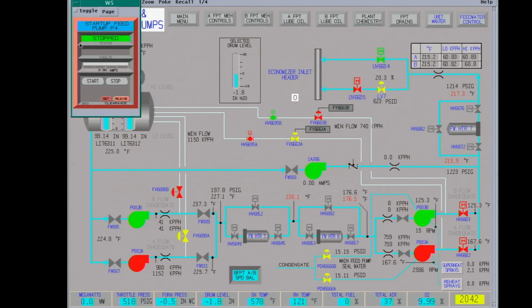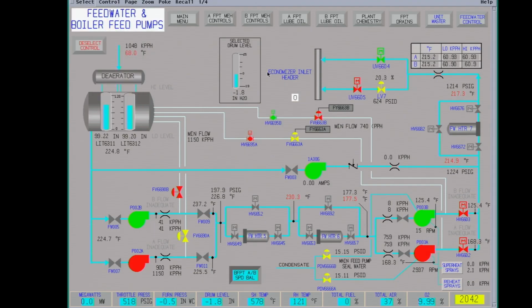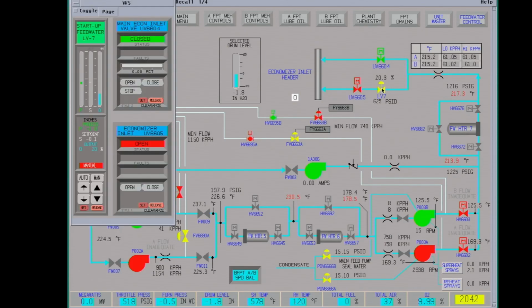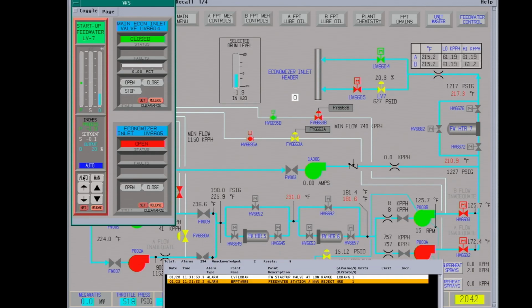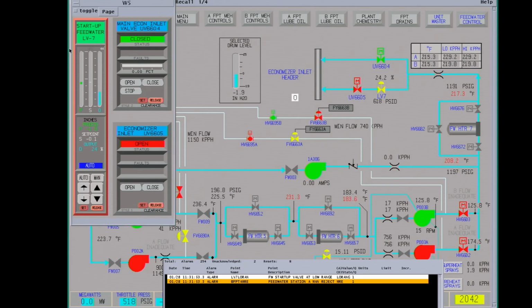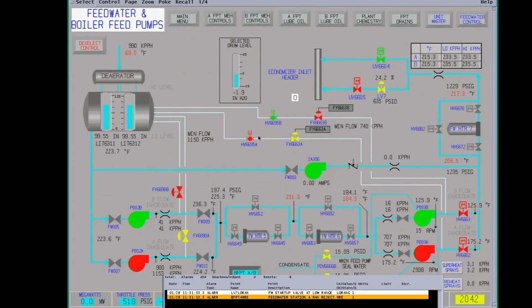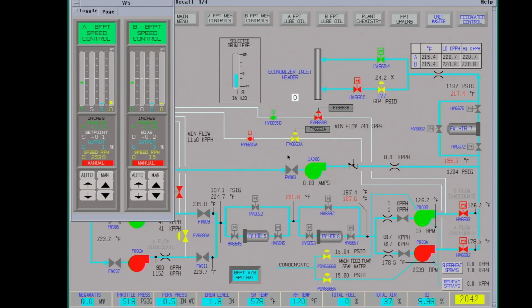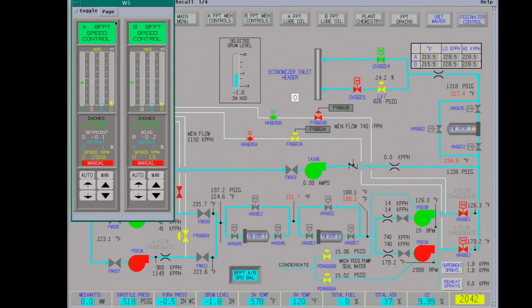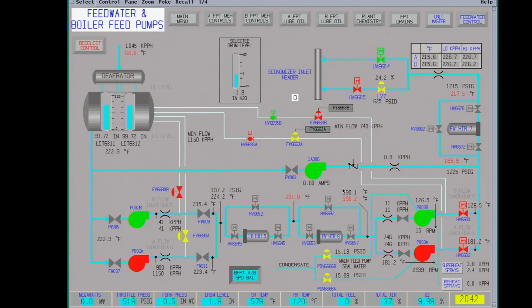We're using more steam now, so we'll have to put a little more fuel on the pulverizer. The level control valve, we'll throw it in auto. Okay, we got a manual reject alarm in. Because you can only have LV7 in auto or the feed pump in auto. We can't have them both in auto. So it's in manual. We just have to maintain a differential pressure across this valve. So we'll play with the turbine speed occasionally. It's just running in manual.